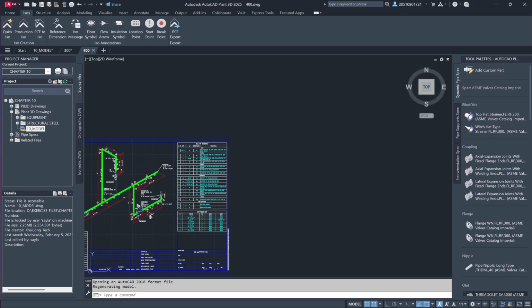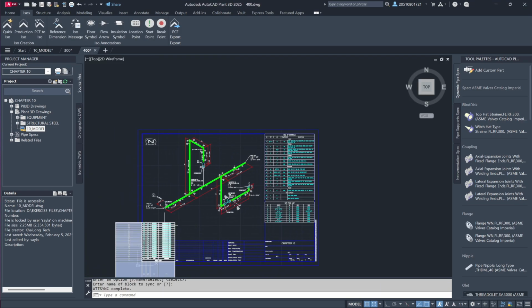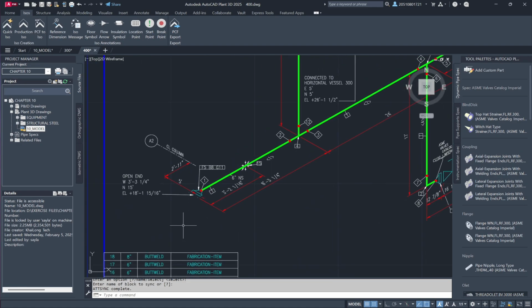Although isometric drawings typically function as standalone guides for pipe fabrication, there are situations where additional reference information is necessary. By incorporating precise reference dimensions, construction crews can accurately position piping components in the field. This ensures proper alignment with structural elements, especially when dimensional accuracy is crucial. Providing these references within isometric drawings is an effective way to convey essential information to construction teams, aiding in the seamless execution of installation tasks.